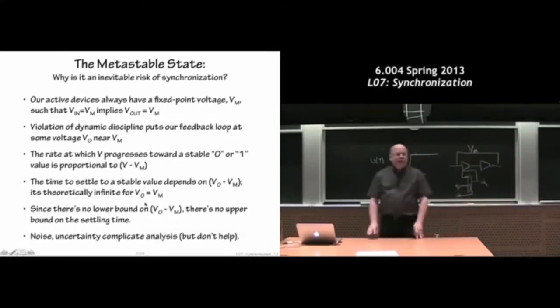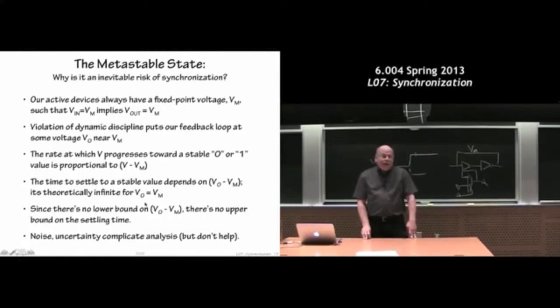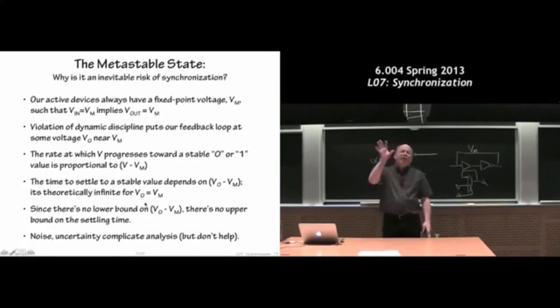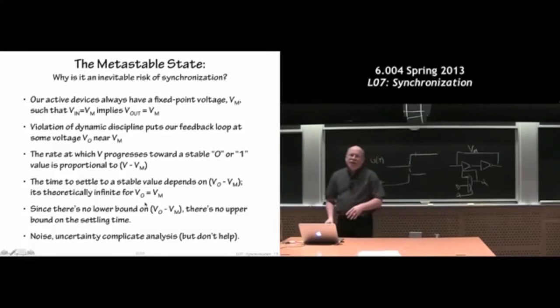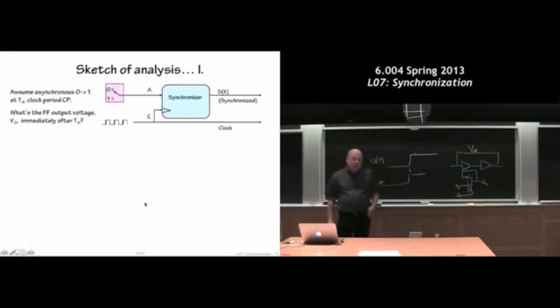You could say, well, that seems like it should work, Chris. The problem is that it certainly complicates figuring out what's going on. You can imagine situations where that would have been fine. It wouldn't have reached the metastable state, but because of the noise, you actually put it into the metastable state. And just as it starts to roll off, you put in some noise which pushes it back. So noise is not a guarantee of solving the problem, because if I get to play devil's advocate, I can take a situation that would have been okay, but noise actually hurts rather than helps.